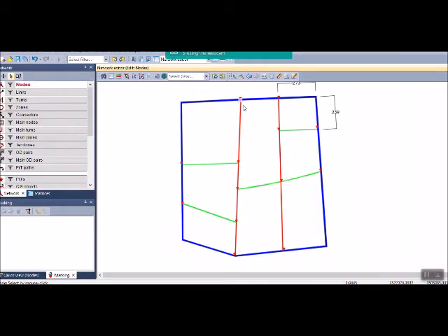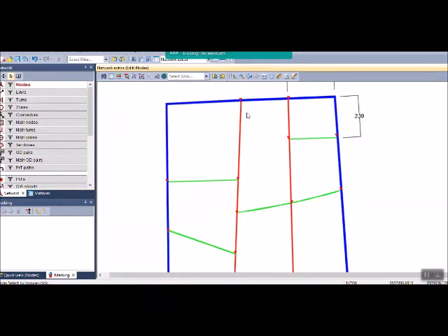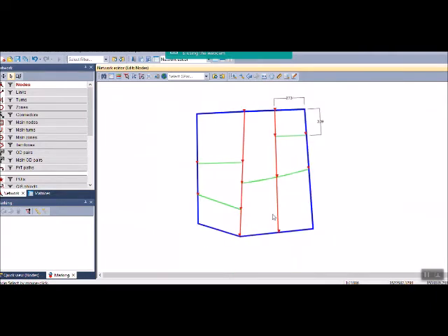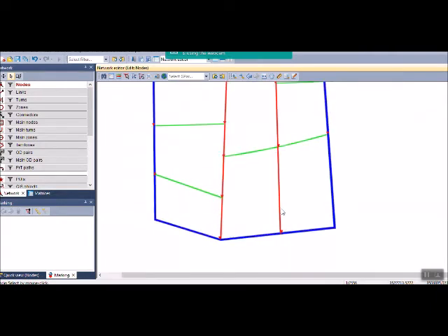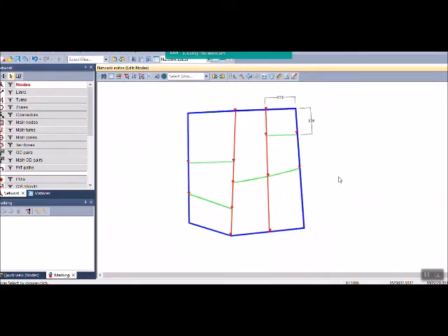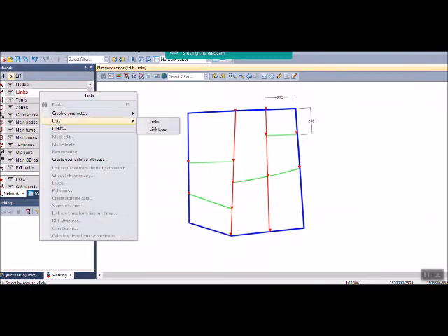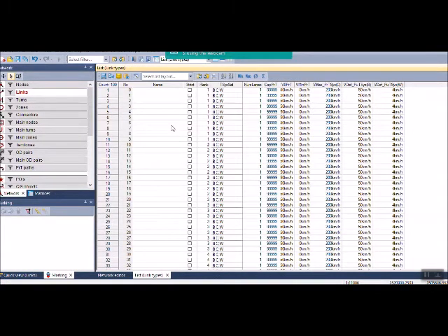Okay, so we defined the nodes now, and you are going to draw the links, which are acting like the roads. But firstly you should define the roads hierarchy, which we talked about in part 1. The roads hierarchy should be defined first. So you go to link, right click and list link types. So I'm going to define the link types I have in my network. I think in the student version this list is empty, but you can add whatever link types you want.